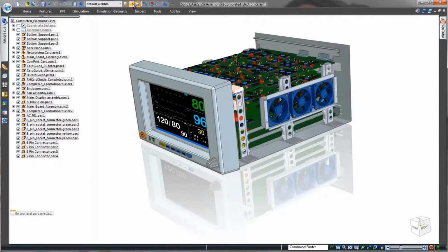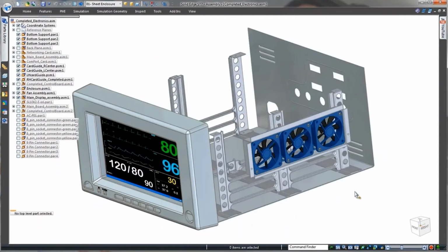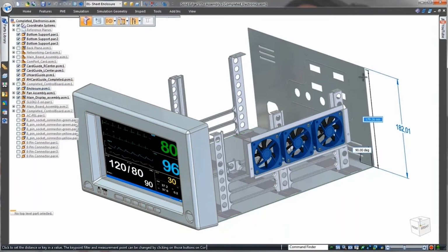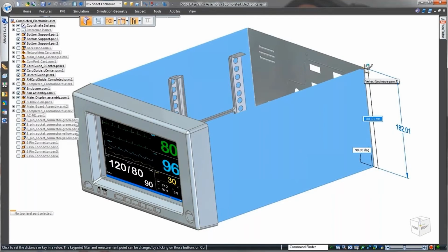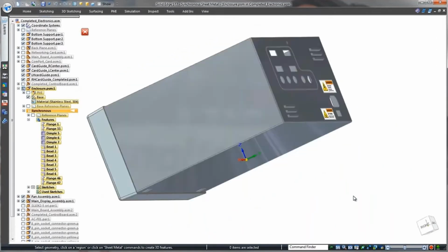We'll use SolidEdge to complete the enclosure of this heart rate monitor. SolidEdge with synchronous technology excels in sheet metal construction, allowing designers to efficiently work with surrounding components to define external product housings. In most CAD systems, the user has to modify a part independently from the overall product assembly. With SolidEdge, additional flanges can be created at the top level assembly just by selecting and dragging the plate's thickness faces. No special command necessary.